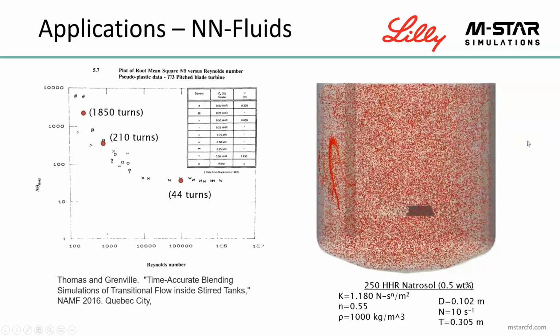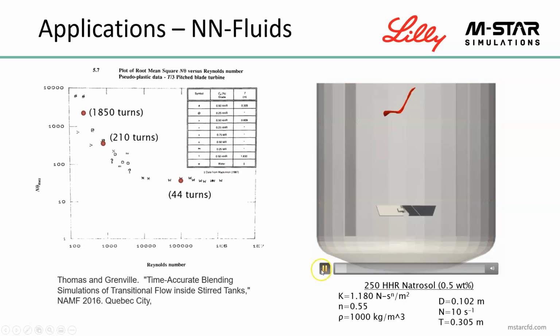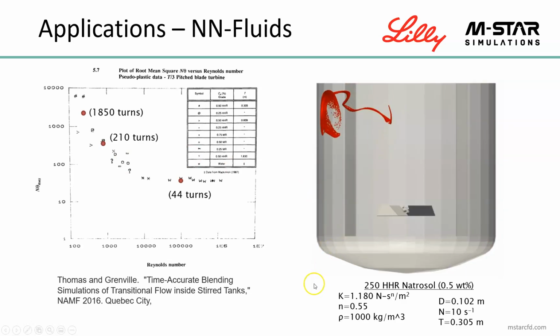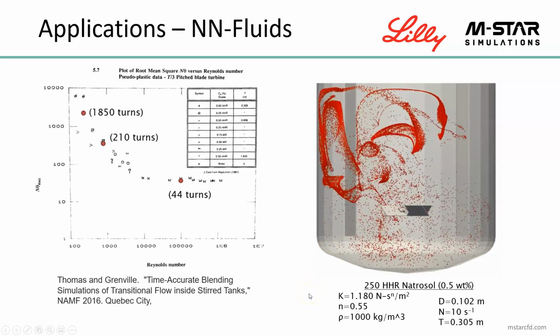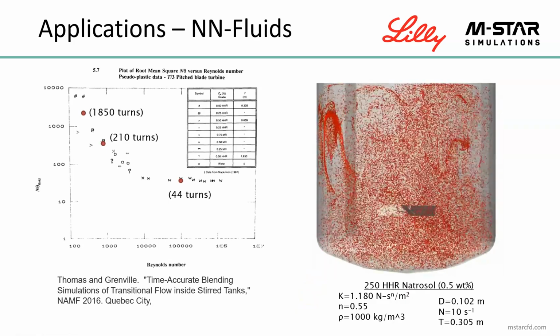And then how do we validate it? Well, we go straight to the tape. We predict the blend time for a system like this and compare it over and over and over again to published data for these complex rheologies. And again, this speaks to this point about when you're modeling time-accurate three-dimensional physics correctly, you can automatically capture what is a really complex process successfully.